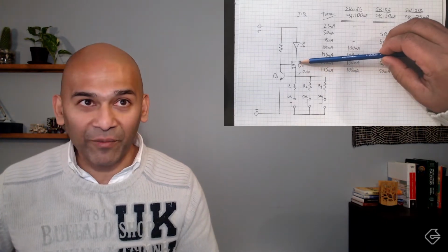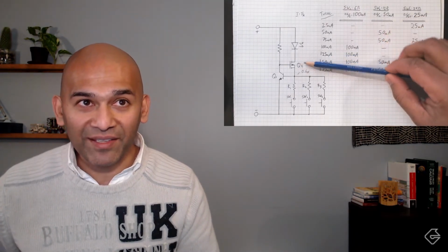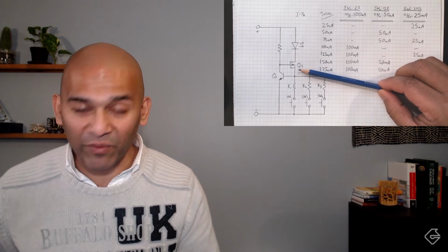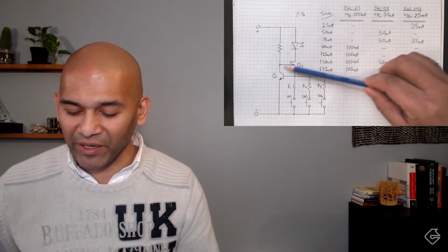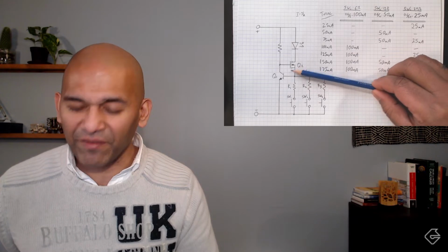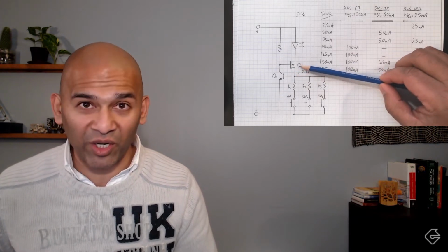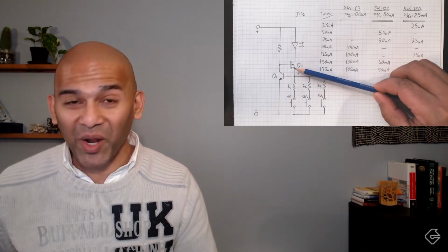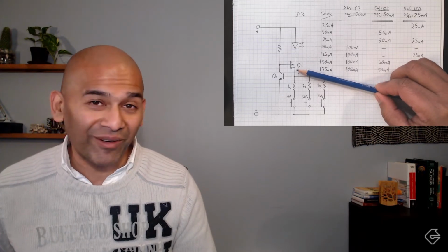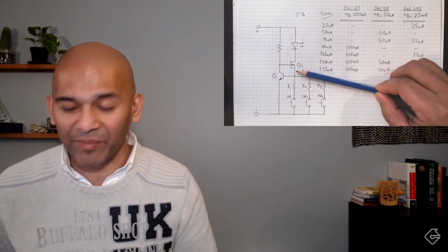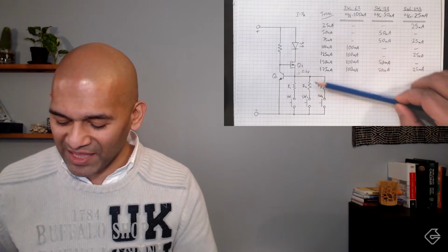This MOSFET that we're using for Q2, this is essentially a valve if you wire it up one way. Now, the way it's working out right here is that this is actually that feedback mechanism that helps control the current that's flowing through our LED, but it can also be used as a valve or as a switch. You can look it up online, use a MOSFET as a switch, and that's what we're going to do here.